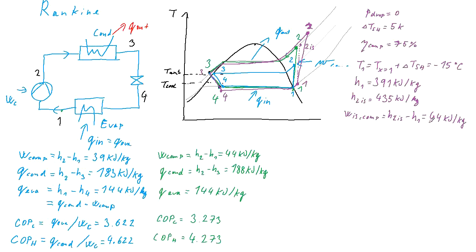We can see that the value is same as over here for the green cycle, because it's between the same pressures, and the difference that the compression work would slightly increase as the pressure difference is realized at higher temperatures is not that high that we would see it from this small temperature difference.